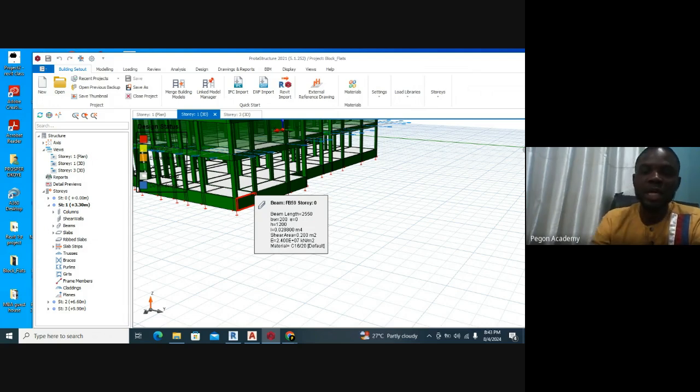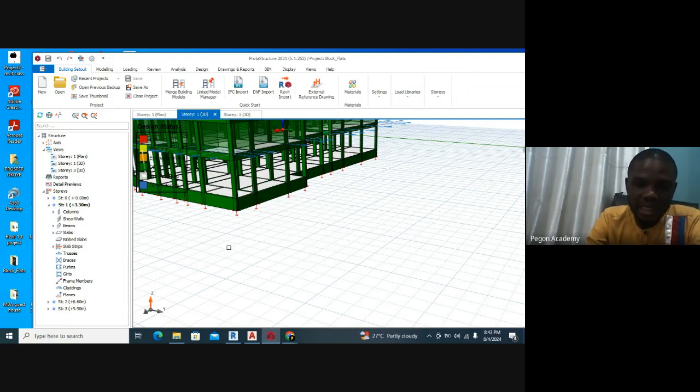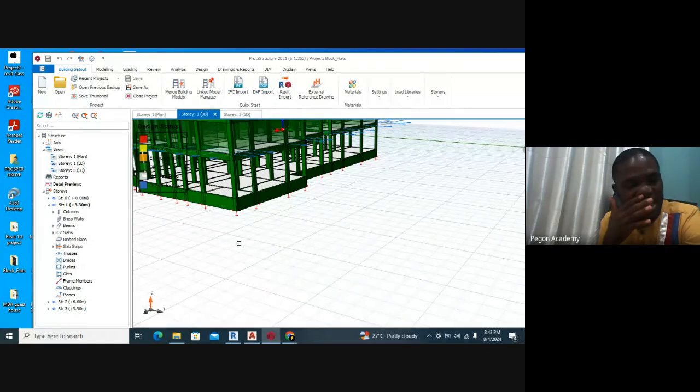So what we do is simply to have a combination of pad and tie beams. Remember the principle: the principle is to make the structure act as a single unit when you have bad soil. So you can just use a pad foundation and then tie them up with beams. When you tie them up with beams, the loads are going to come from the columns down to those beams and then down to the pad. So in a way, the structure is still acting as a single unit.